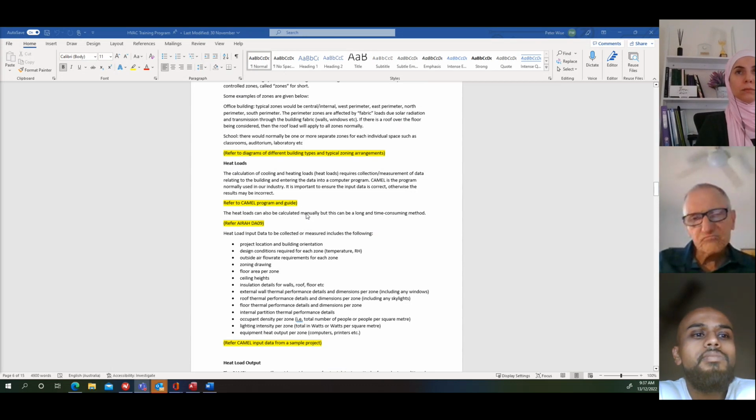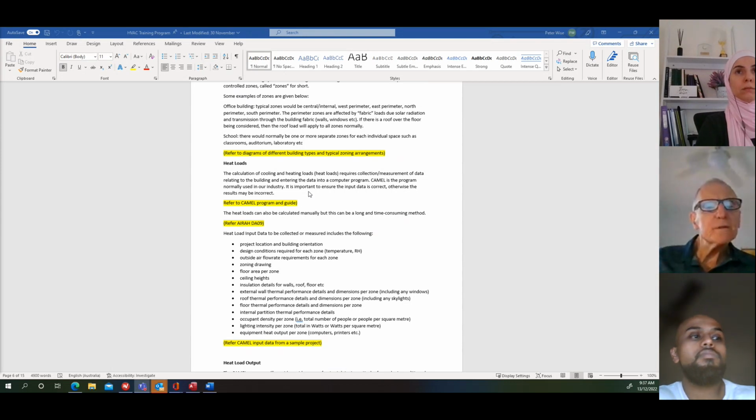Sometimes it's not easy to get, but to do the heat load accurately, you need to get this data, and you need to get that right. Now, you can run the heat load with preliminary data. The longest time is taken by actually entering the data. So you can put something in, you can do a preliminary load, and when you get the correct data, then you can replace the data you've already got.